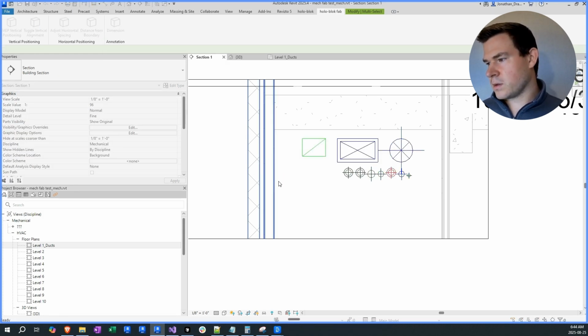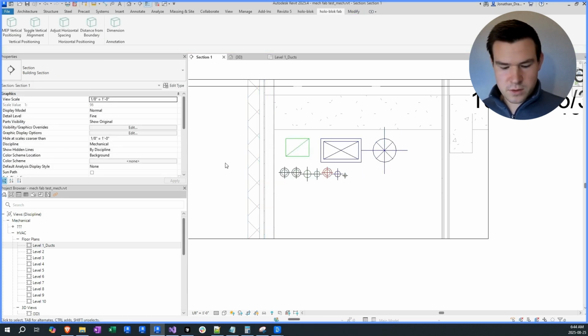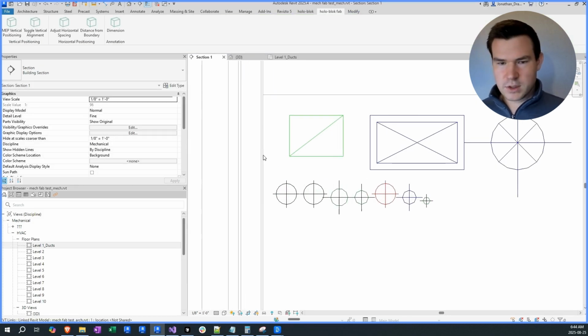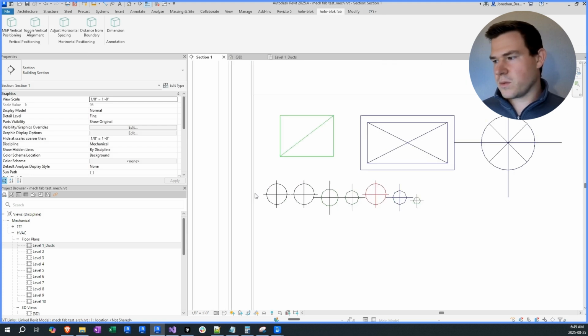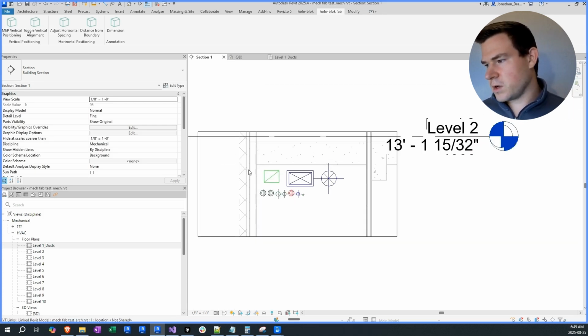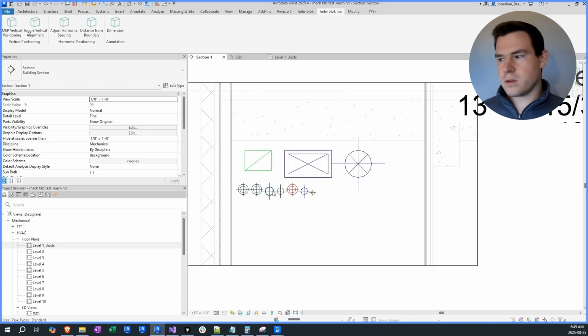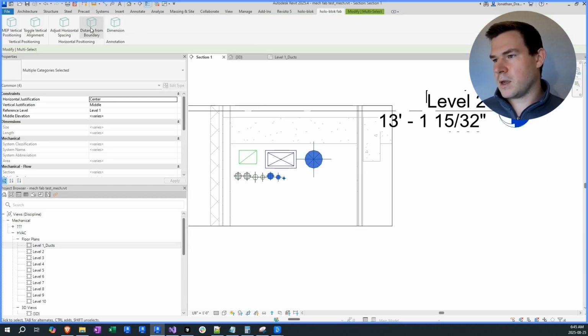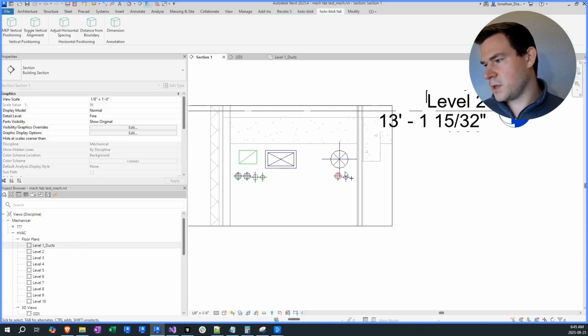Just select the wall, and they're all going to shift over, where right now we have it set so that there is 8 inches from the duct to the wall, 4 inches from the nearest pipe to the wall, but that could also be configured. And if we don't want these all aligned to this wall, we could even select a few pipes and say this duct and set those to be spaced from the wall on this side.